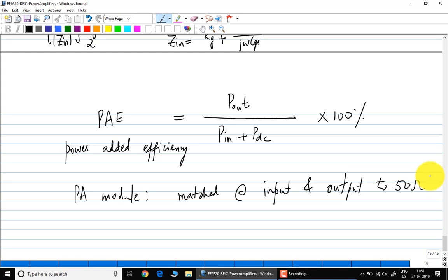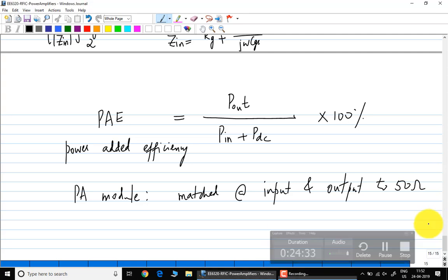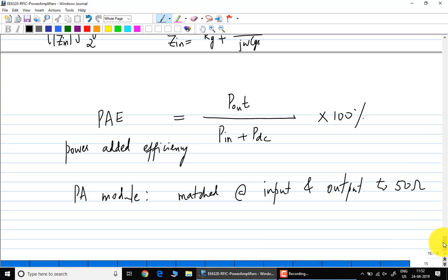Input power is always there, it is not just that Rg is very small. The minute you match the input, it has a real component of 50 ohms, you are delivering power. Then it depends only on the power gain of the module, S21. Does that make sense? If S21 is very large for the PA, then again PAE will approach drain efficiency.